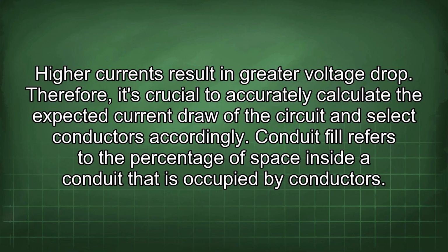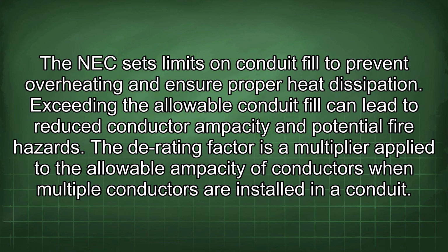Conduit fill refers to the percentage of space inside a conduit that is occupied by conductors. The NEC sets limits on conduit fill to prevent overheating and ensure proper heat dissipation. Exceeding the allowable conduit fill can lead to reduced conductor ampacity and potential fire hazards.